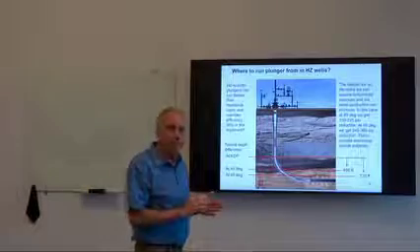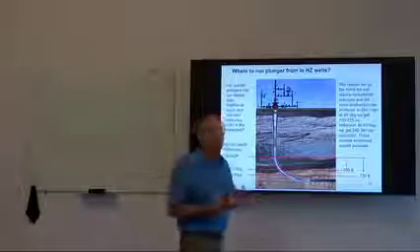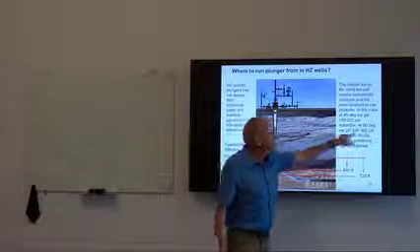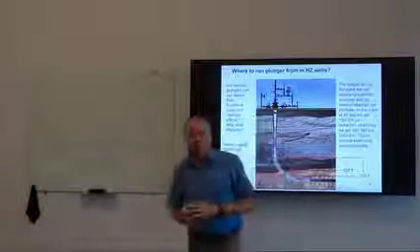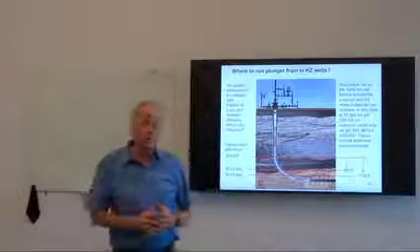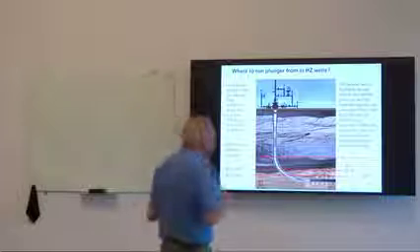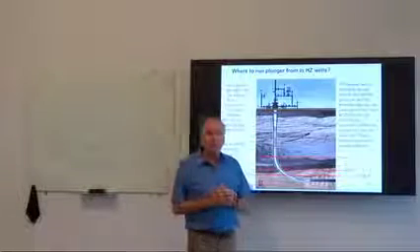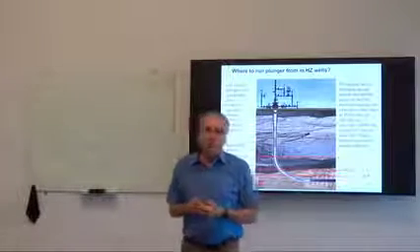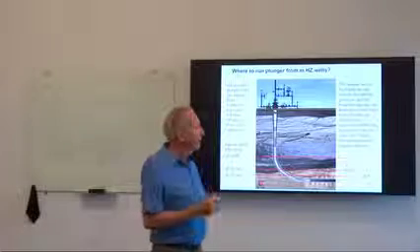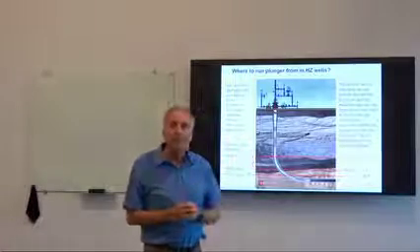And that's an opportunity to increase production from the well. At 60 degrees, that range is even higher, and I'm showing 240 to 360 psi of potential pressure drop. And that has enormous consequences for the productivity of a given well.